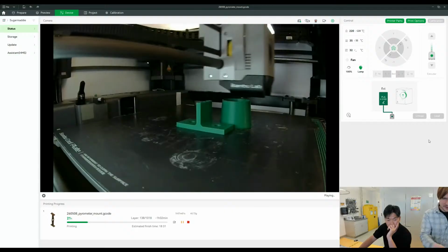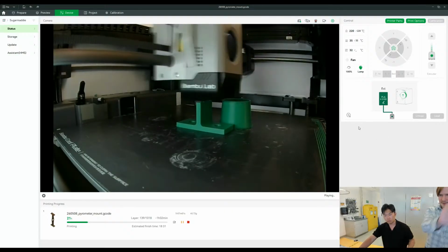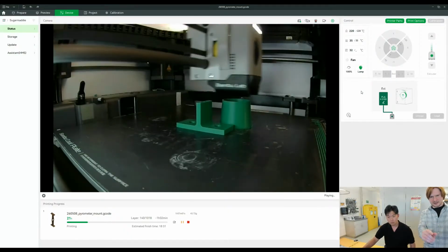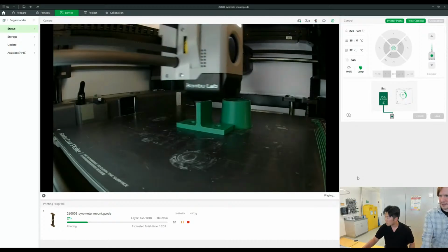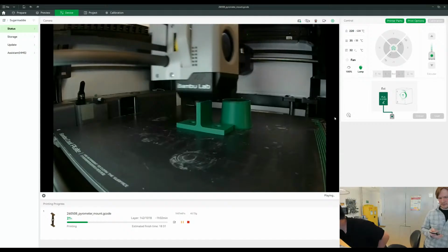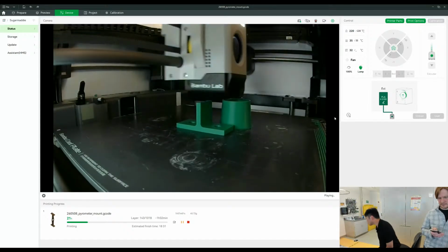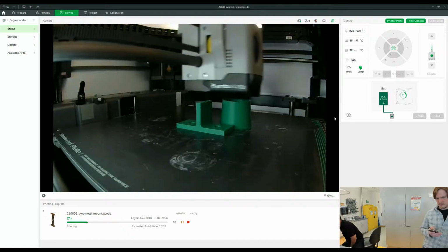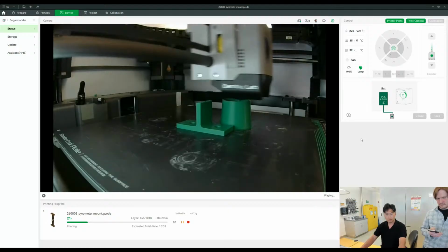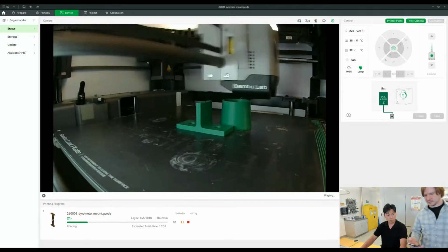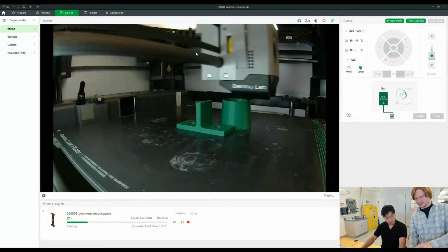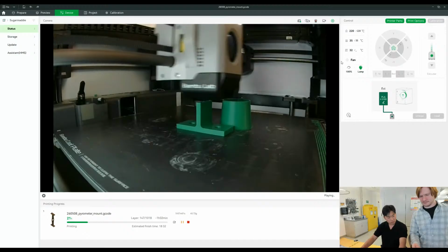But the phase angle controller is taking a little sliver of each part of the sine wave. On each complete wave, it's taking a little bit of this one and a little bit of that one, varying that proportion. It's sampling a little bit of each wave. So basically, that's your burst fire, with one on and one off. And that's your phase angle, sampling a little bit. You can vary that infinitely.